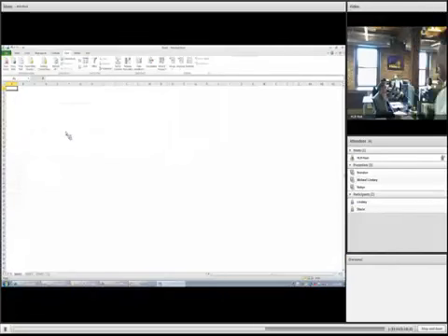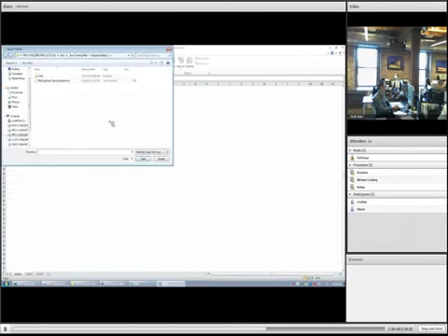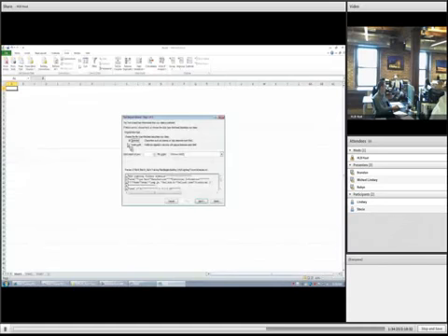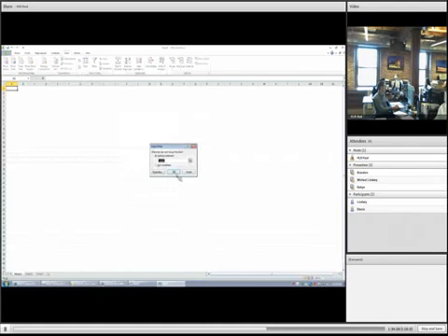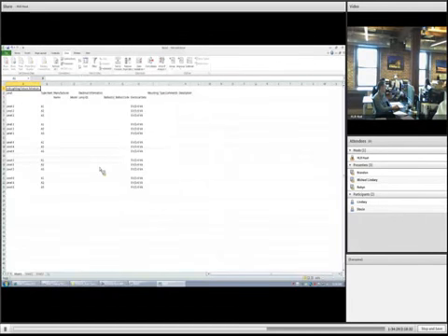Okay. In a blank workbook in Excel, you can just follow this quickly. I would imagine everyone has Office 2010, and Excel 2010 is really nice. Because it comes out as a text file, you'll hit From Text, which is on your Data tab. Browse to your text file. You'll hit Import. Just accept all the defaults here. I generally just go to Finish and then hit OK.